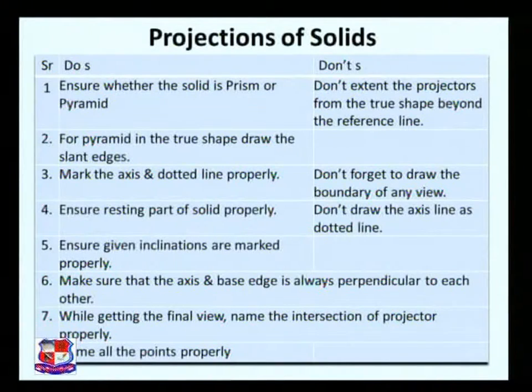Now some do's and don'ts for projections of solids. What you should do and what you should not do for drawing projections of solids. First, ensure whether the solid is a prism or pyramid. Don't extend the projectors from the true shape beyond the reference line. Second, for a pyramid in the true shape, draw slant edges.